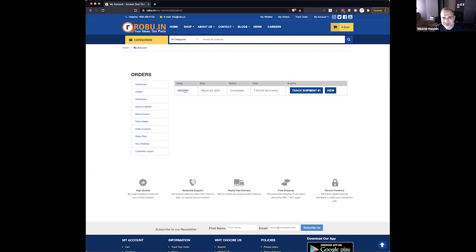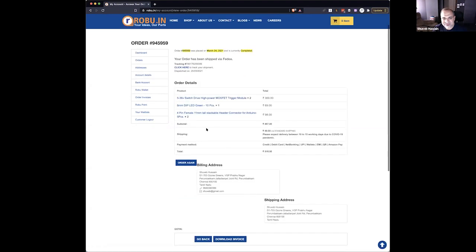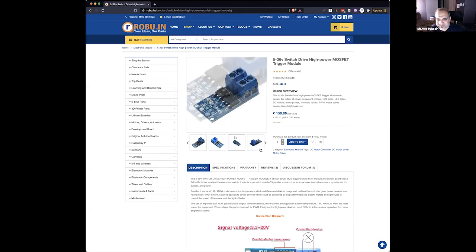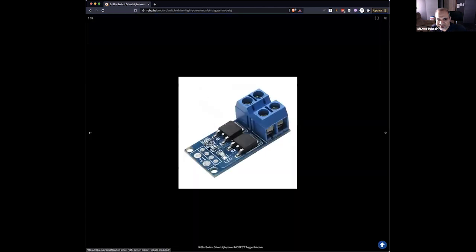Yeah, so I recently ordered this. It's on the way. I can't wait for it to come. If you take a look at this, here is a PWM. You see this here, J1. This is where you provide PWM input, and then here you provide power. I think this can do up to 36 volts, so it can control LED strip lights easily. Mine is a 12-volt LED strip light. So you input 12 volt here, and then you connect your device here. This is input, this is output, and you have PWM here.